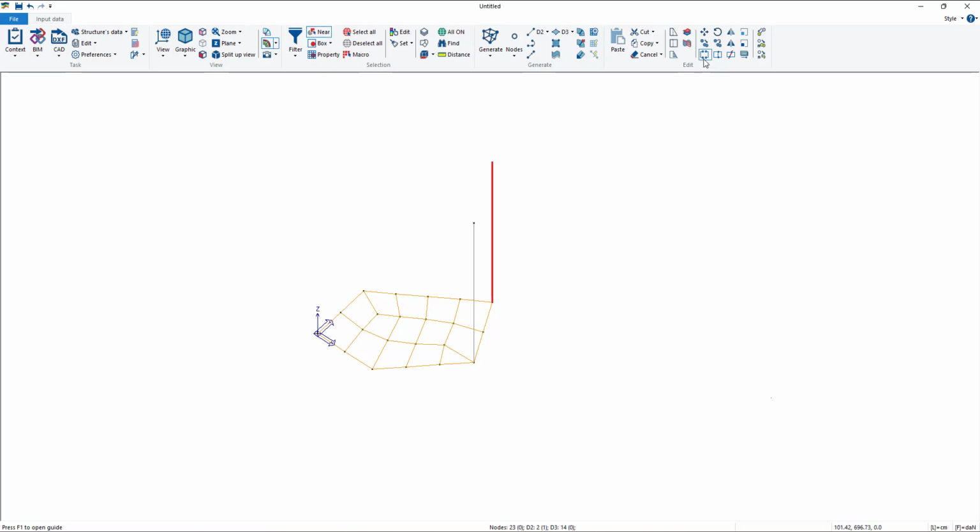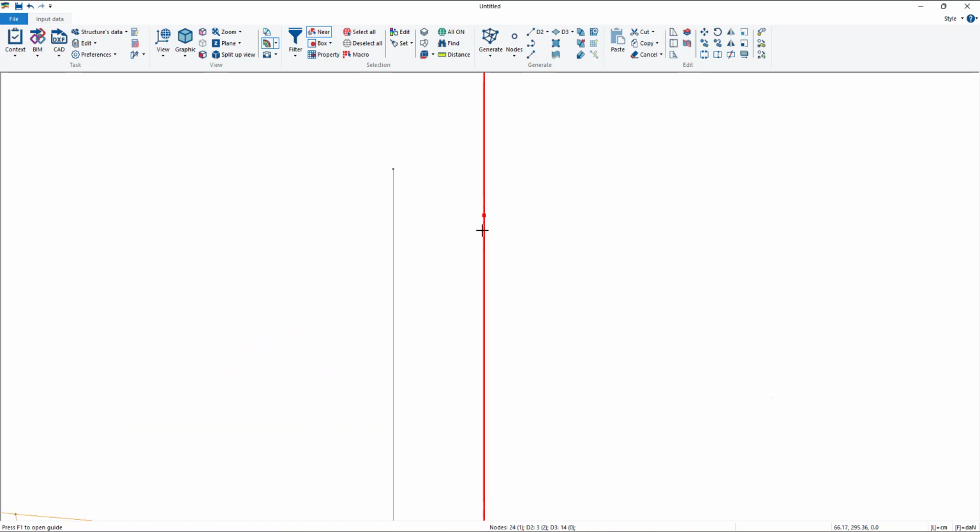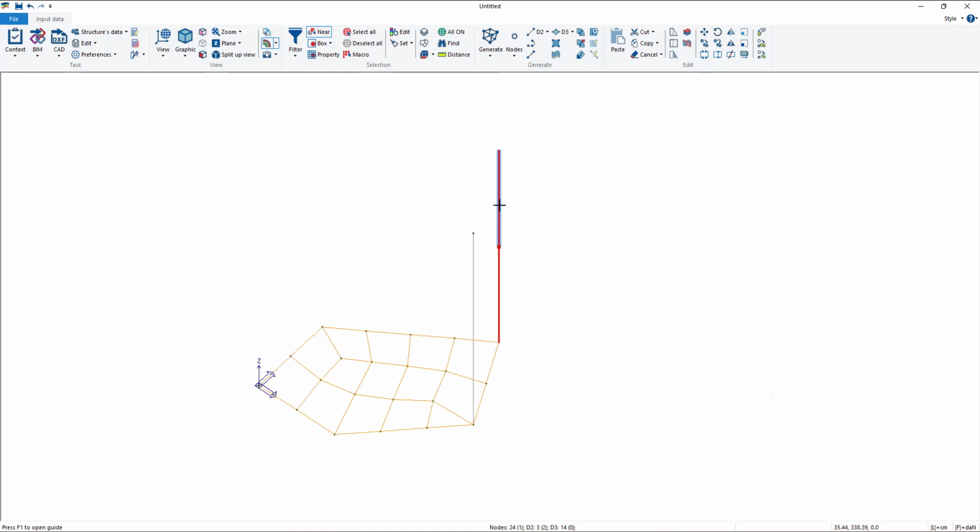One that can be useful is divide. That basically divides selected elements in equal parts. So if I go divide, you see that a node has been created there, and if I go here, these are different elements separated from this. If I go again on divide, it's going to divide the single elements in two parts. So divide basically divides each selected element in two equal parts.